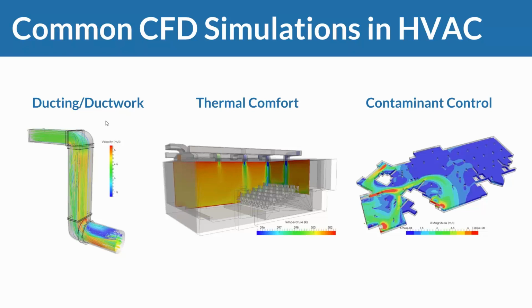We oftentimes see that in industrial building designs where you have a large HVAC system or a large ducting system that needs to, I don't know, supply a large hall with fresh air or get it out there. And there the pressure drop across the ducting system becomes very relevant, right? It becomes a relevant sort of design parameter for the building.